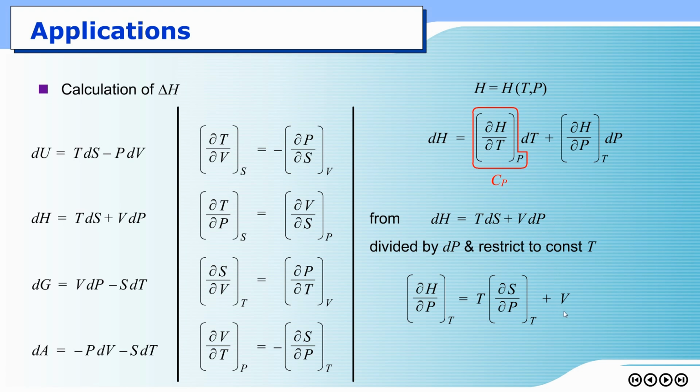Okay. You might wonder, what would happen if instead of using this fundamental relation, I start by using this equation instead? Can I solve to something useful? The answer would be no, unfortunately not. Because if you start with dU on the left hand side and repeat the process, you will end up with dU by dP at constant temperature, which cannot be related to something that we know.